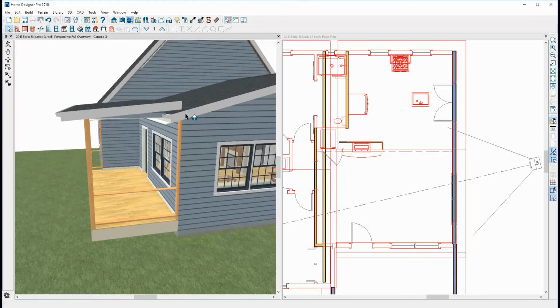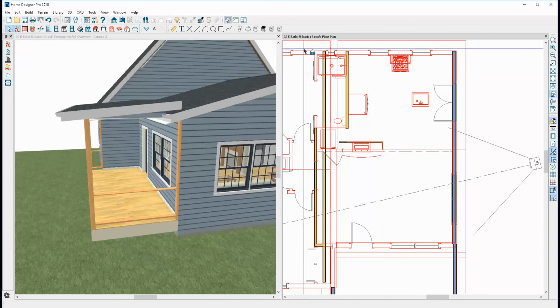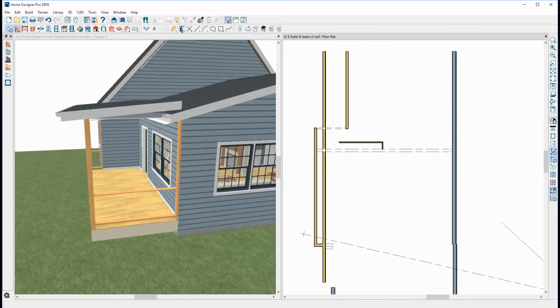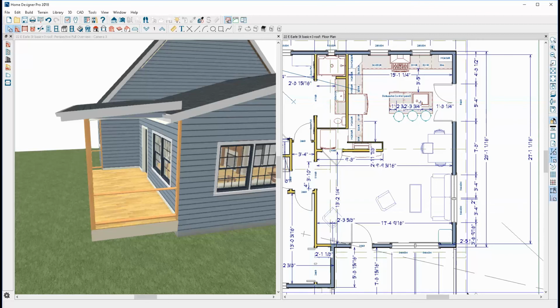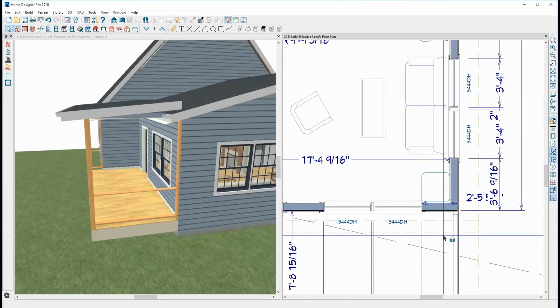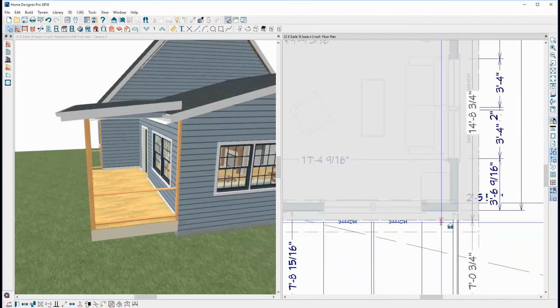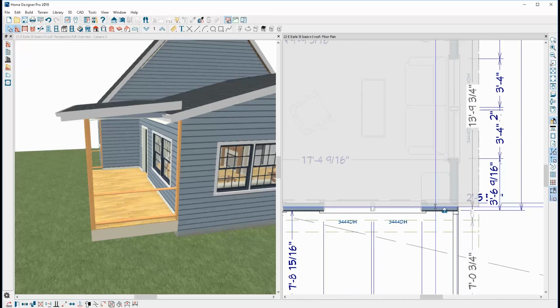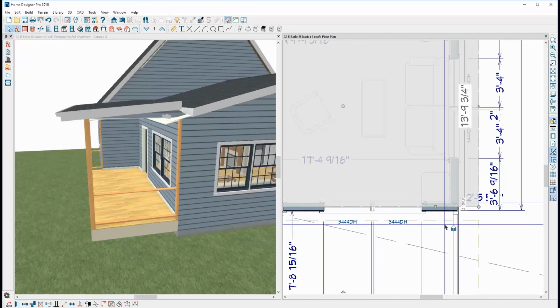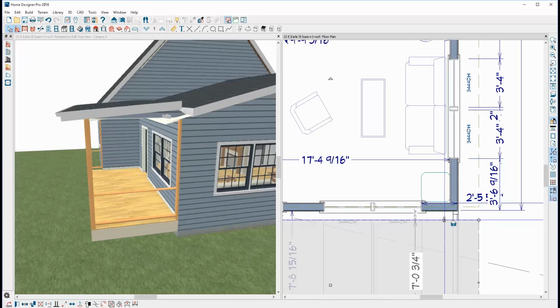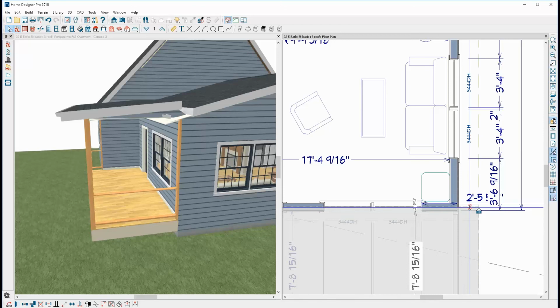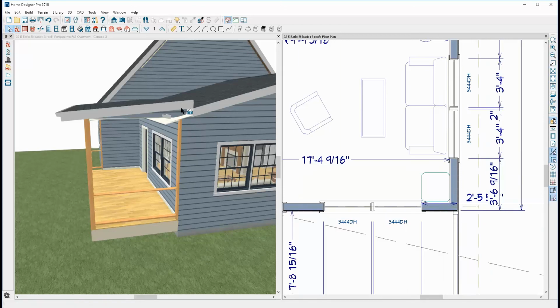And what I'm going to do to remedy that, I'm going to go back to plan view and turn the reference display off. Go back to the first floor. I'm just going to manually set this roof over the center of that wall, and the shed roof I'm going to put over the center of that wall. Let it just snap to the edge. Yeah. So that they're collinear, but one's higher than the other.